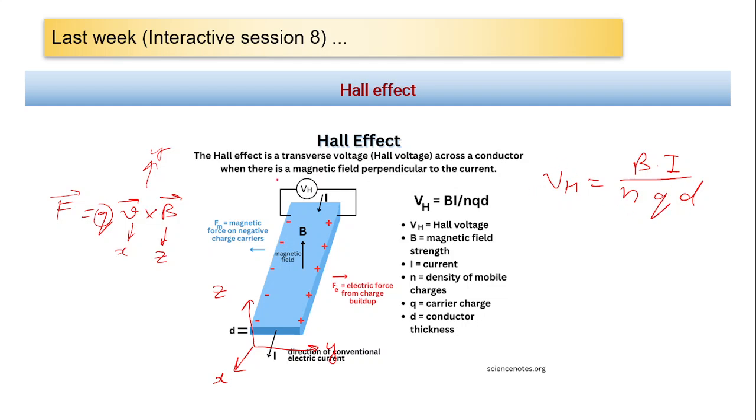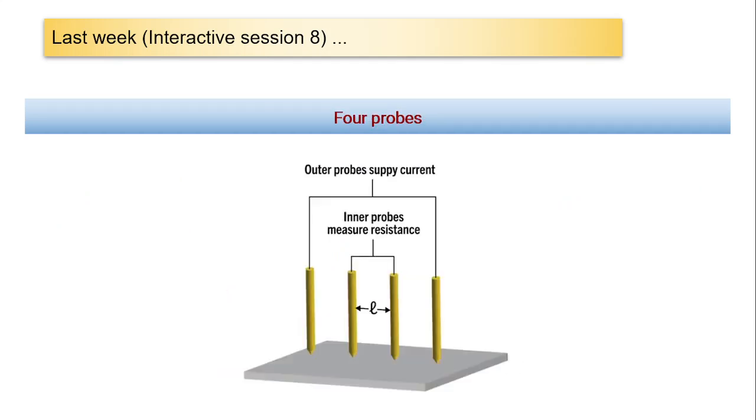So this, and furthermore, there is use of this Hall voltage experiment. Another thing we had seen is how 4 probes help us get error-free resistance for a sample, especially when a sample has a very small value of resistivity like metals or some semiconductors, and thus 2 probes may result in a lot of error in the value, whereas 4 probes help us eradicate this situation.